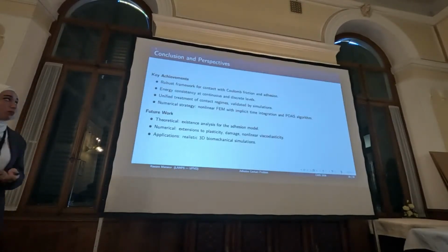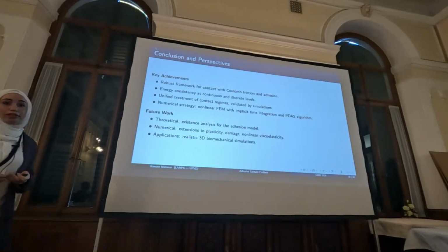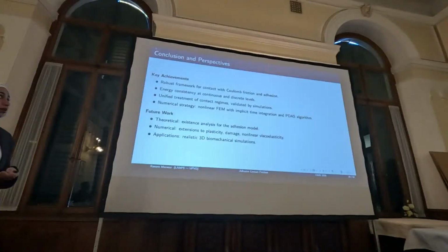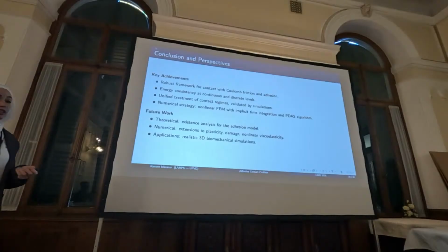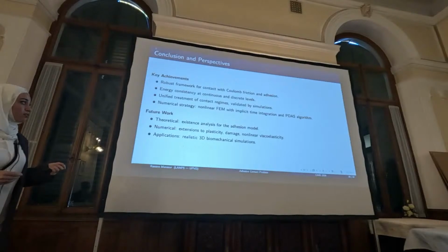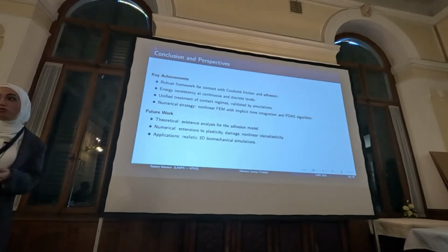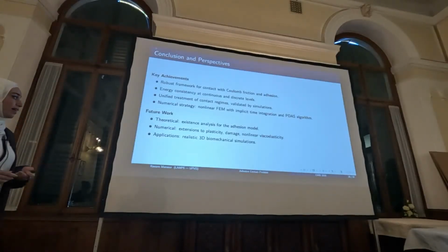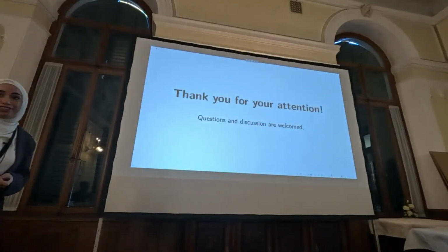This work represents a robust framework for contact with Coulomb friction and adhesion. It ensures energy consistency at the continuous and discrete level, and it provides a unified treatment of contact regimes validated by simulation, while the numerical strategy is based on the nonlinear finite element method with implicit time integration and the PDAS algorithm. Future perspectives include theoretical analysis of the existence of solutions, numerical extension to plasticity, damage, viscoelasticity, and application to realistic three-dimensional biomechanical simulation. And thank you for your attention.